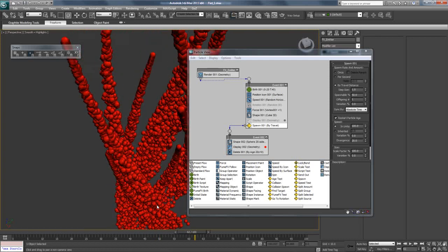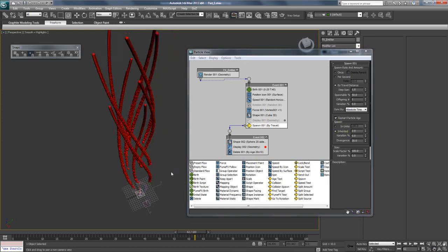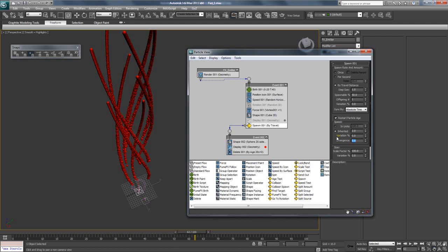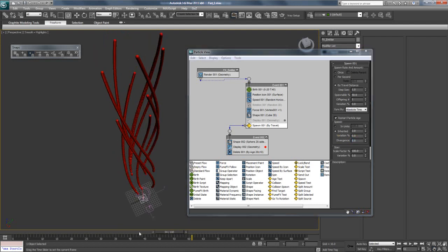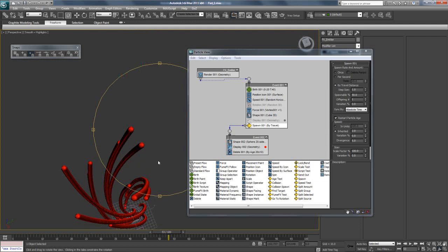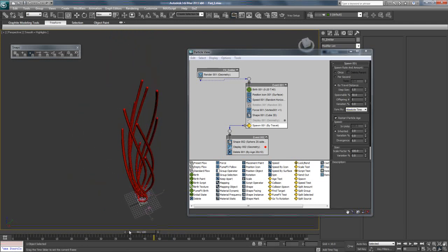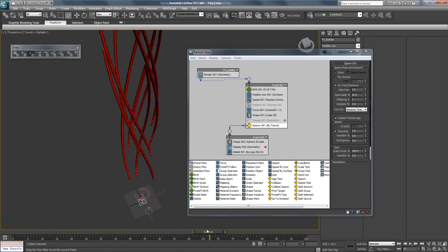So something like this, I can save this, because in case I have to do some sort of missile effect, like these ballistic missiles happening and stuff like that, I know the settings to use. So I'm going to change the divergence to 5.0, so it wasn't as much, and you can see the difference in the values when you change them, what happens to the particles, and how close they stay together. So we have the lines going so far, and this is pretty much the first step on getting the effect we want. We just want to make sure that the particles are not spreading, because it looks weird. We want to create basically these linear lines.